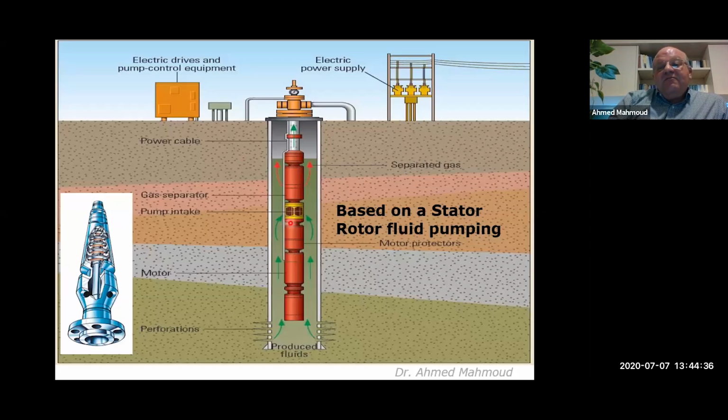Before the rotation, the fluid passes through a pump intake, which is like a separator, and it's a very important part. It needs to separate so that you don't take in a lot of gas and get cavitation, because the ESP can only work at its best when there is not a lot of gas being taken in. If you take in a lot of gas, the actual mechanical system can be damaged.